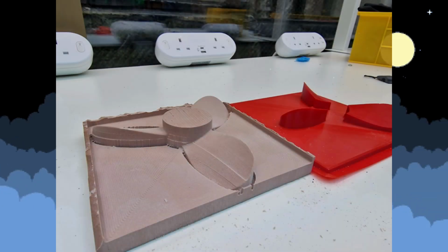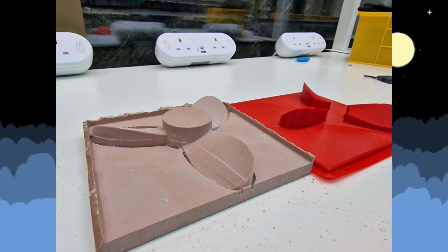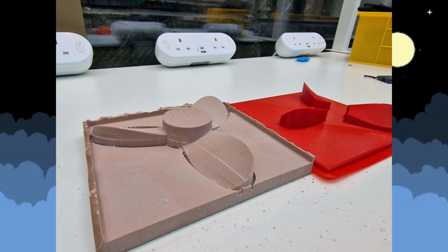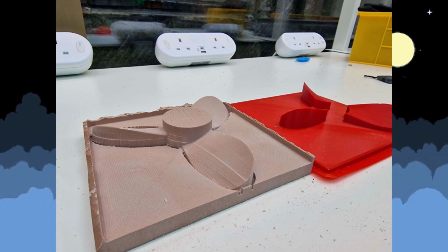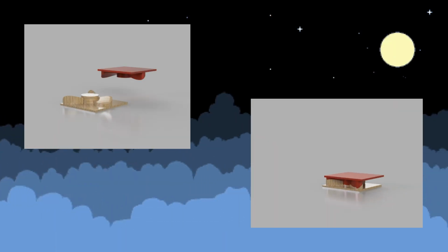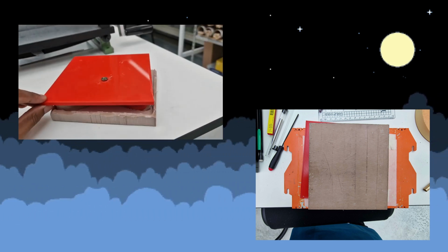The machine itself is 3 axes, and thus only half of the propeller can be produced within one go, as the 4th axis isn't available. If it was, it would be able to rotate the entire stock, simplifying the process a lot. However, by creating a negative inverse of the propeller through the use of support lobes, it would have been possible to create the other half of the propeller. However, more issues were faced when doing this section as well.